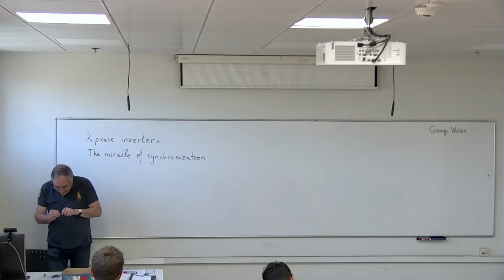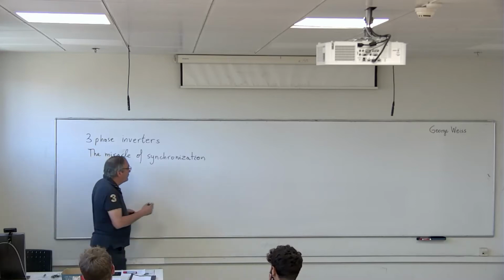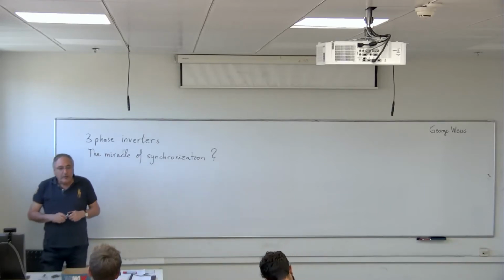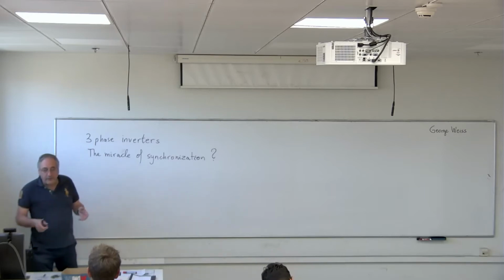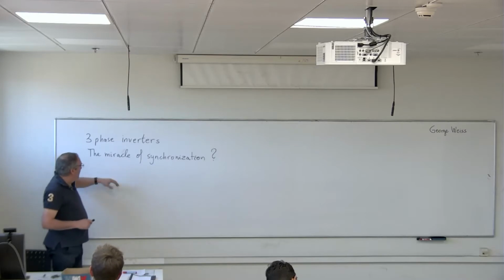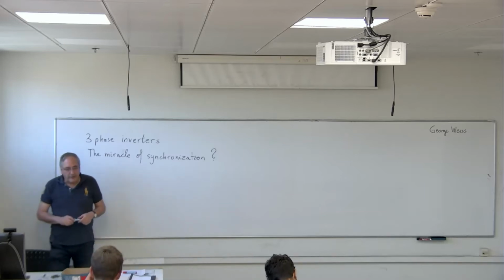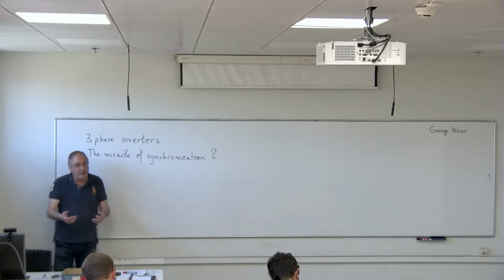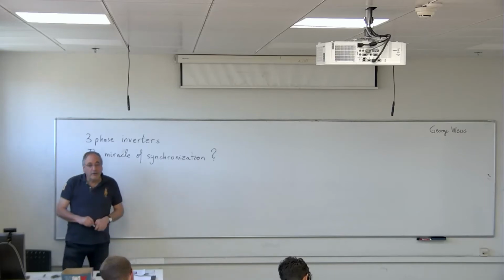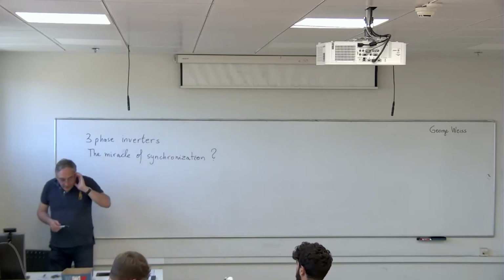And in short, the answer is that mostly this is not true. So, of course, it depends how the inverter is controlled. You have many different algorithms for controlling an inverter. And for most of the algorithms that are now used, this will not be the case, which means that an inverter knows to synchronize to a given grid. So if you have an already existing powerful grid and you come with an inverter, then of course, every inverter that is commercially available knows how to synchronize itself to this given grid and then inject power according to the power requirements that the user can tell this inverter how much power to inject.